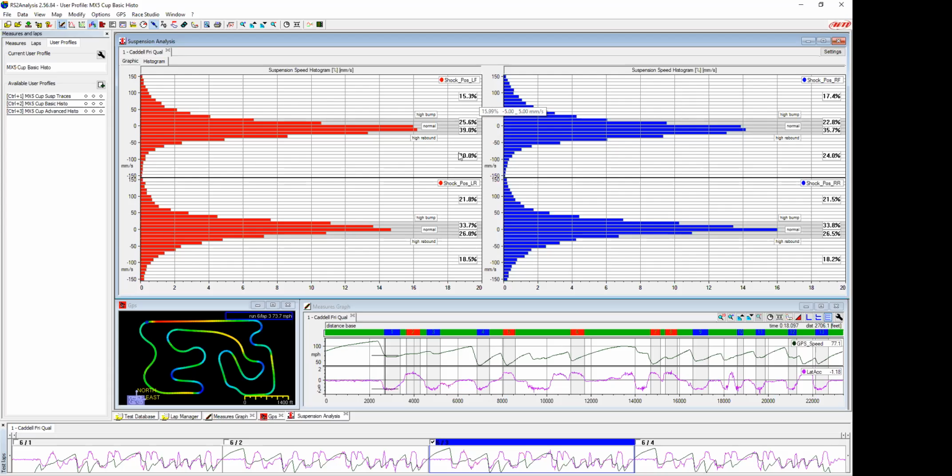25, 25, 25, 25. Every time you get back to the start finish line to end this lap and begin the next, your shocks and all of the settings are probably right back to where they were at the lap previous. So as you're traveling around, you really do want your shocks to more or less control the car. You will find some tweaks here and there that will make the driver feel better, but a great place to start is a balanced amount of compression and rebound, both low speed and high speed, and that's where you might want to start.